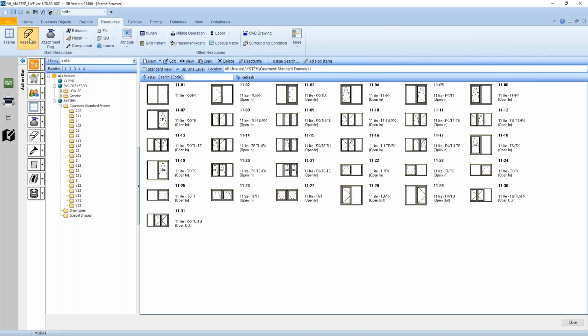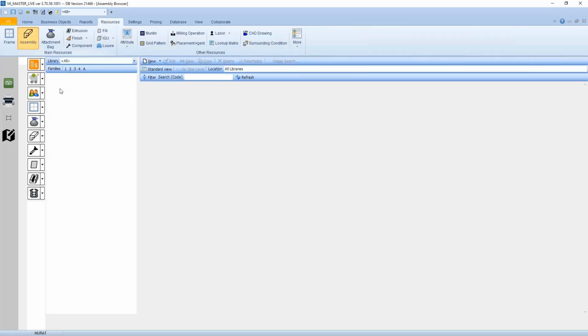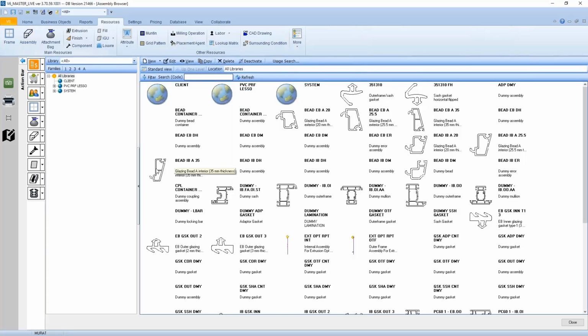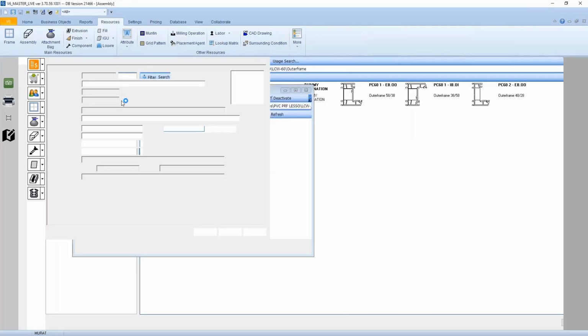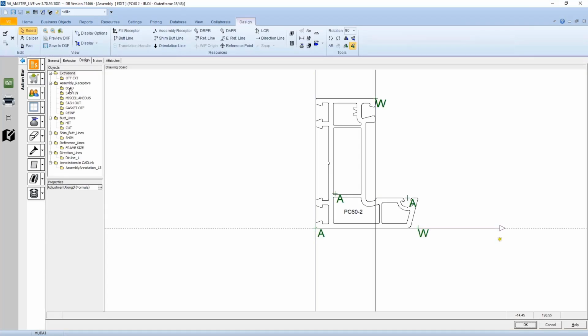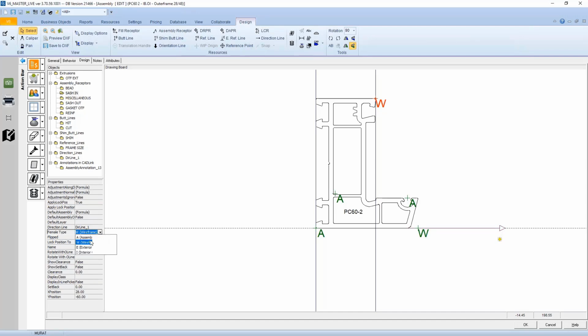So if I come here and open back my author frame. Yeah, the receptor type, female type, here should be A if you want to use this default assembly functionality. For W, although the property is there, it will not have any effect. So yeah, that can be used for that purpose.